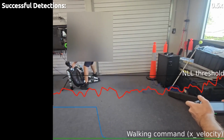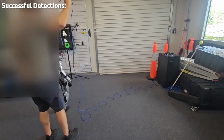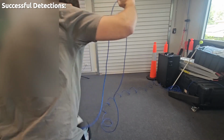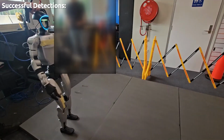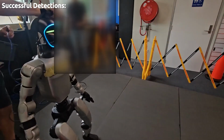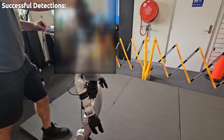As the robot continues moving despite near-zero velocity commands and its gravity-aligned roll drifts, RAPT cuts the policy before uncontrolled behavior occurs. We observe similar early detections across a range of real-world anomalies, including heavy payloads, deformable terrain collisions, and external pushes. In each case, RAPT intervenes before the behavior becomes unsafe.